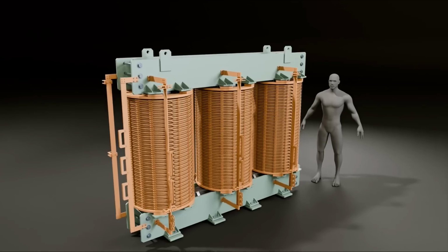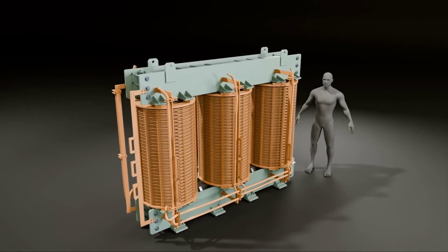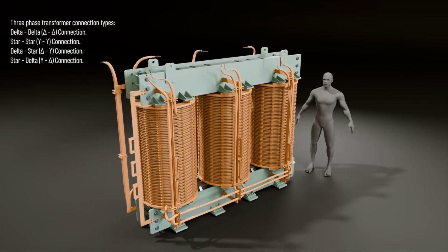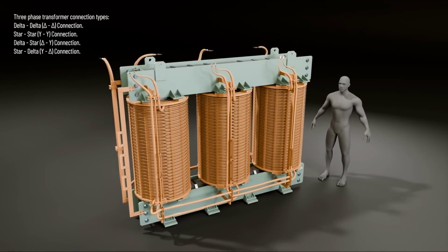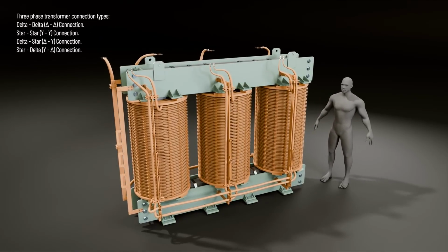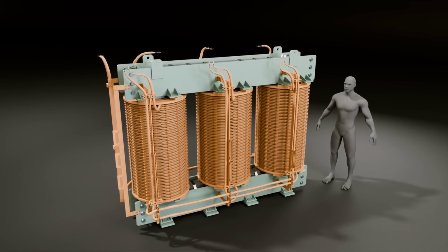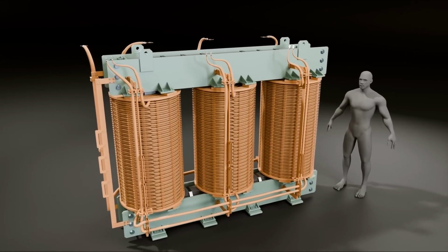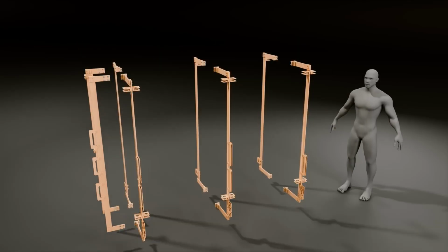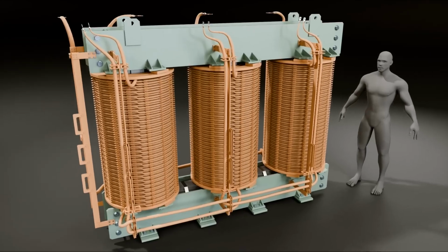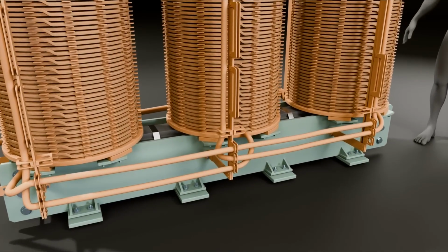Power transformer windings are connected in either star or delta configuration, depending on the design of the transformer. We will discuss star and delta connections in a future video. In a power transformer, a support structure made of insulating materials like pressboard is used for providing mechanical support and electrical insulation. Crepe paper tubes and SRBP tubes are employed for ensuring secure and effective connections.